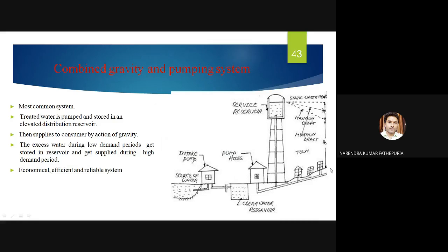So, and the town is like this, suppose. Gradually the pressure will decrease as you go away towards the consumer end. That's why the pumping station is needed, because near the tank, near the reservoir, pumping is not required. The gravity water will supply because sufficient water head is maintained, as we have put the water at a very great height, 20 to 30 meters actually. This tank, like this, in a clear water reservoir.